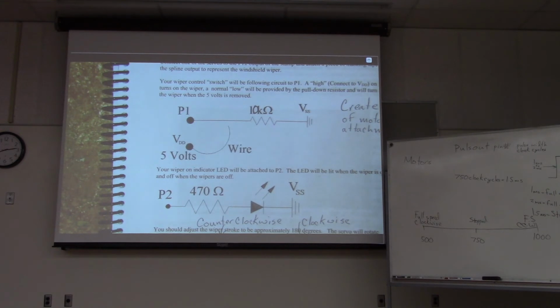So, I noticed that the motor was pin 12. But there's also the pins on the breadboard that go up to 15. So how do you distinguish between that pin 12 and the other pin 12? There is no difference. They're actually electrically connected to each other.